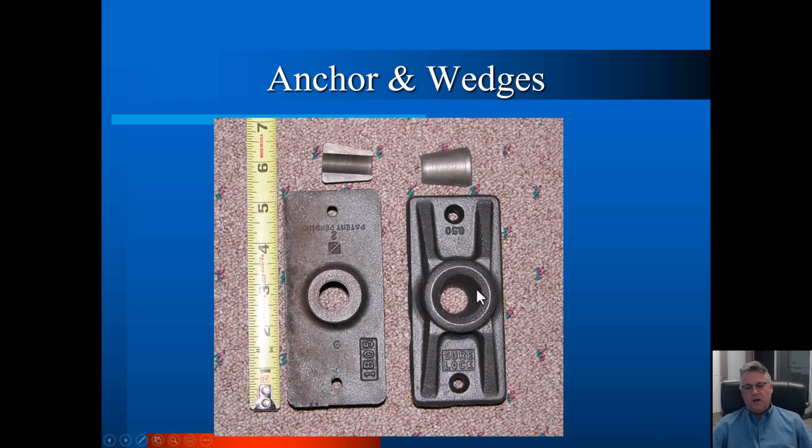But as the strand comes through, the wedges are placed, and the strand is literally stretched, not just taking the slack out, but stretched, the old PL over AE that you all learned, in order to get the force into the tendons. And every half-inch diameter tendon will have about 28,000 pounds in it initially. So when it's trying to recoil back through, these wedges will hang up, lock up, and keep that from happening.